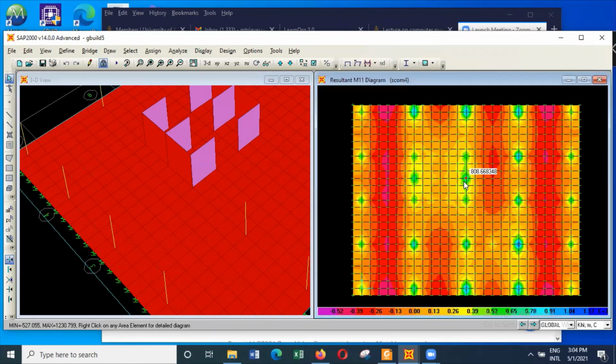a thickness selected based on the bending moments. And when it comes to shear, it's possible to use vertical reinforcement to carry shear at local failure places, whereas in other places the concrete alone will be able to carry the shear. So this is how you can deal with it.